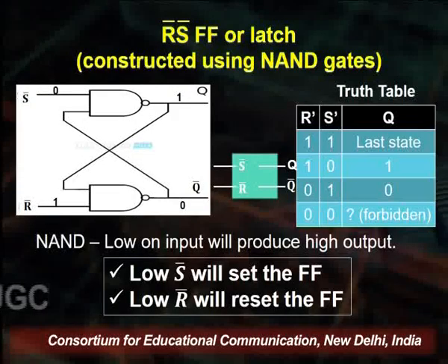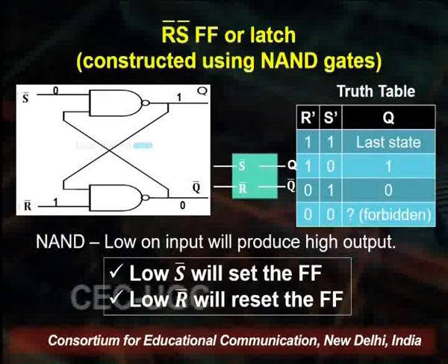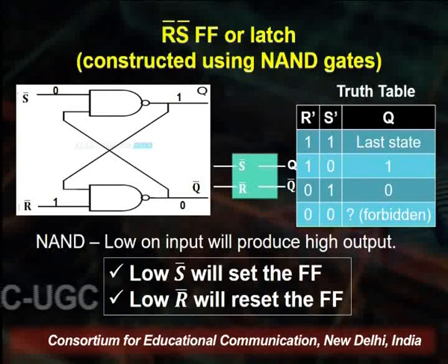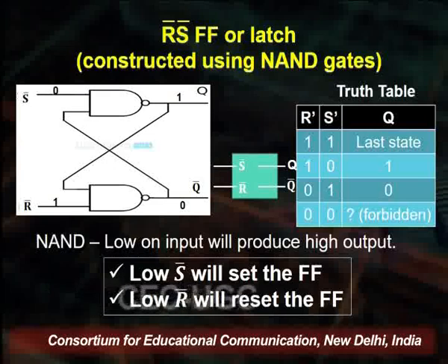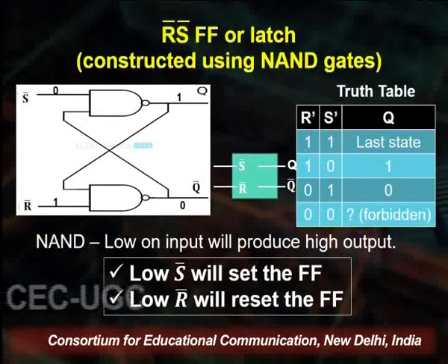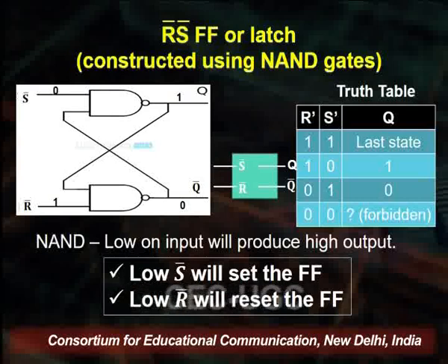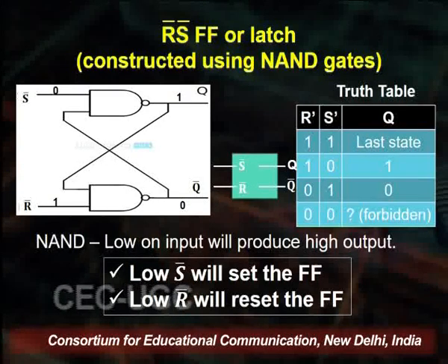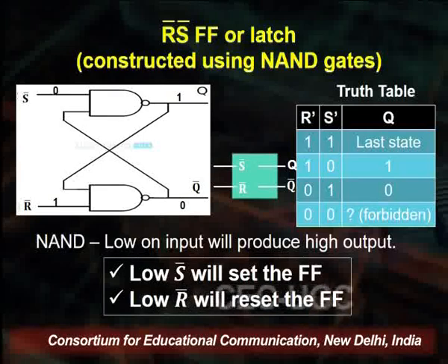We understood how the RS flip-flop worked, and we saw that it could be realized using either NOR gates or NAND gates. Why the preference for NOR gates and NAND gates? That also we have discussed previously, since these two gates are universal gates. We prefer the NAND gate because in this part of study we concentrate on sum of product solutions. With NOR gates we get product of sum solutions.